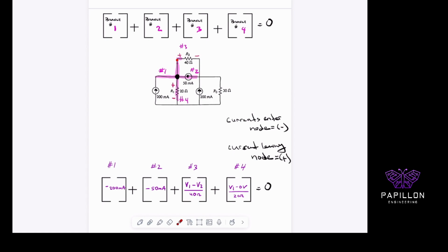The third branch, which is this one over here, it's really important that you get that one. So let's do this one slowly. So the third branch, if I recall from how we started off, this is my node 2, which is on this side over here. So I'm going to draw that in purple on this side. So what happens is that with this particular branch, I am evaluating node number 1. So I have an unknown voltage of that node. At the end of the day, we're trying to solve for the voltage of that node. The voltage of that node, which is my voltage 1, node 1, is going to have a potential difference between that branch and node number 2, which is on this side. Okay, and all of that over R.